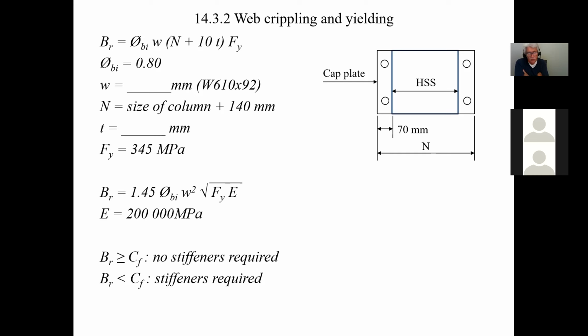Yeah, obviously you have to choose the 600. You can't go less. You understand? So based on the KL of 5,600, you got your CF value, you found a CR value. You checked to see which one was the lightest. I checked. This is the only one I could have found. Anyway, if that's what you're going to live with, Omar, that's what you're going to be putting in your calculations and in your drawing. Then once it gets submitted, I'll let you know if it's right or wrong.